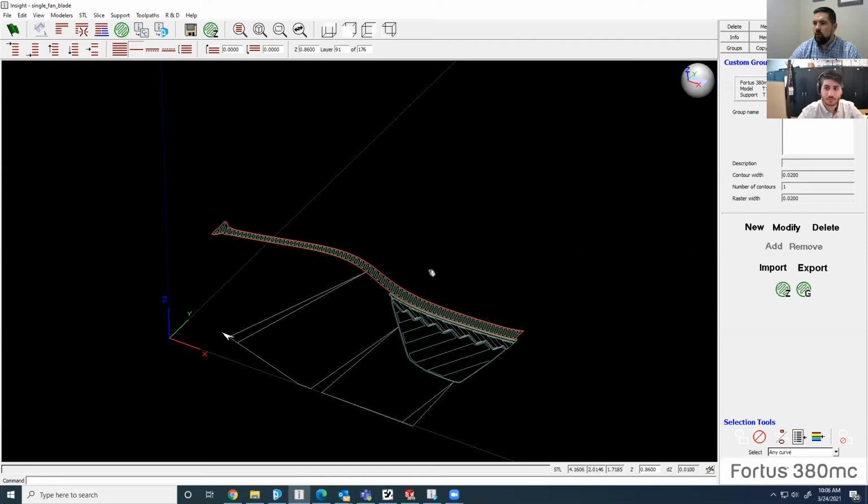And as we go through that, we had one more question, Colin. What do you recommend to build more often, in ABS or ASA, and why? I try to use ASA as often as possible, just for the fact that it is UV stable. So even if you don't plan on taking it outside, we have parts in our back room that we use day to day that are made out of ABS before ASA was created. And just from light coming through the windows, they've begun to yellow.